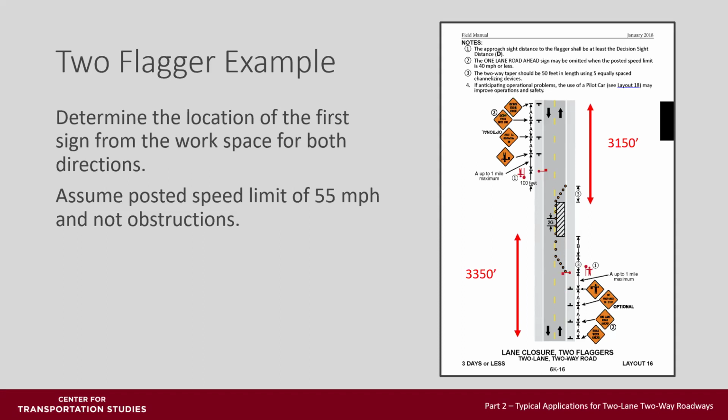For this example, we assume that there were no sight restrictions requiring adjustment of device locations, so these devices will work. In many cases, you'll have to adjust the locations accounting for intersections, driveways, curves, hills, and other field conditions. Typically, you would increase sign spacing while making these adjustments and reduce channelizer spacing to better define the vehicle path.